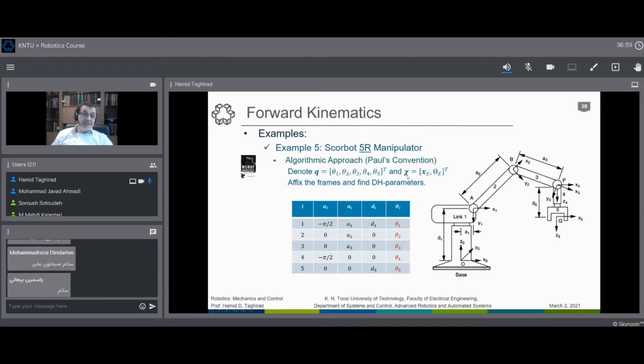The task manipulator is not complete. It is only 5. Three of them are the position of the end effector, and 2 of them give partial orientation of the end effector. And in many applications, we don't need rotation about the axis of rotation.